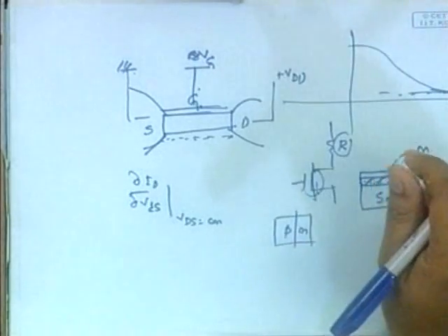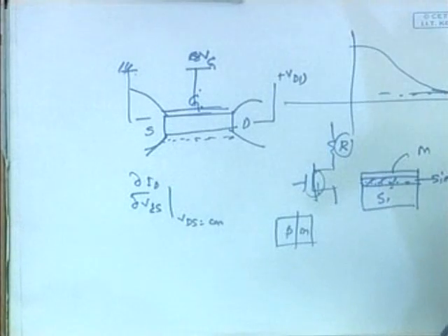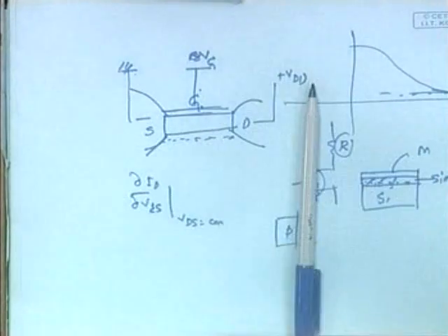I will explain at normal temperature, say 27 degrees, that is 300 Kelvin. So you understand how the physical process, the physics model, as well as the device and the mechanism at high frequency is finally governing my noise incorporations. In analog, you only know the thermal noise, 4kT R delta f. You are happy with that.